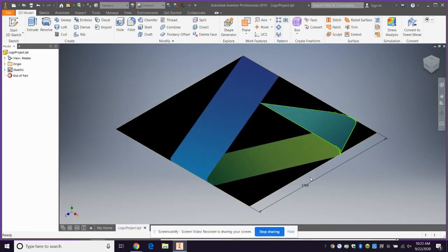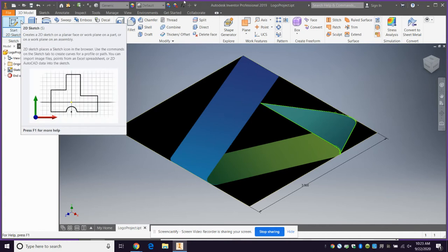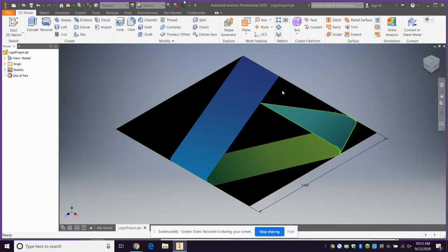All right. Now the big thing here is, when you come back to a sketch that you were already working on, you don't start another sketch. This is a mistake kids make all the time. They start another sketch, and they'll complete it, and they'll say, "Wait a minute, why is this connected to the other part of the sketch? What's going on here?" Because it's a different sketch. You can't connect drawings between two different sketches.